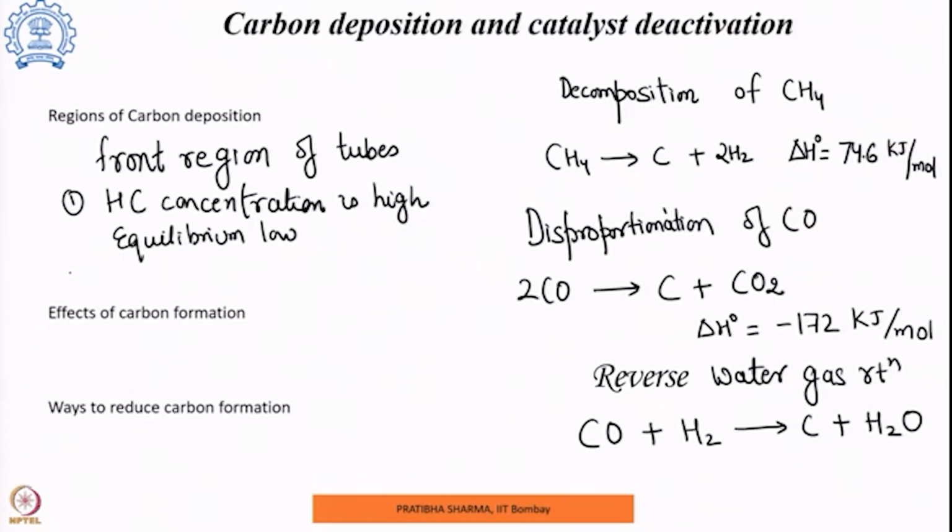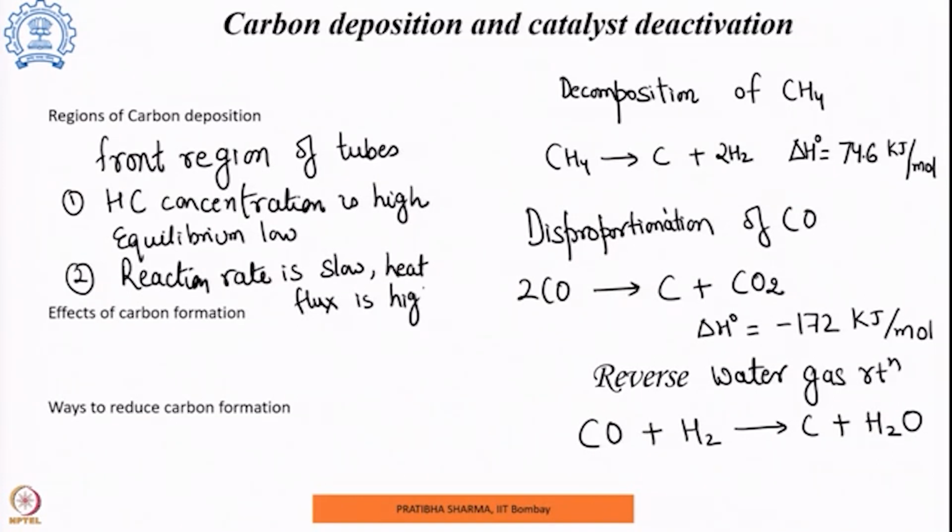The reaction rate at the top of the region is slow. However, the heat flux is high. So, as such there could be carbon deposition onto the catalyst.